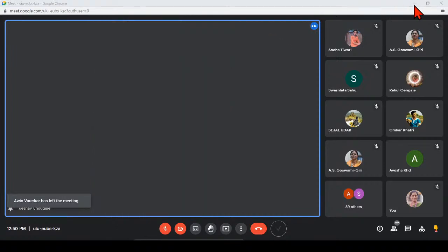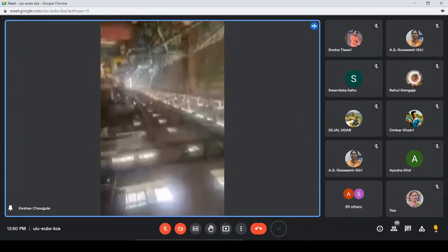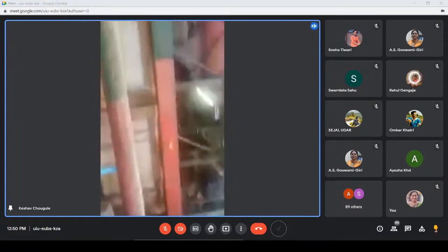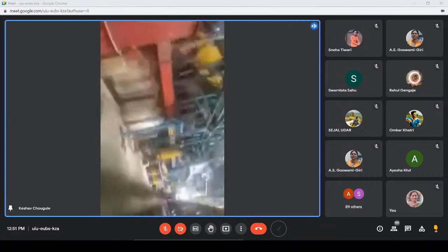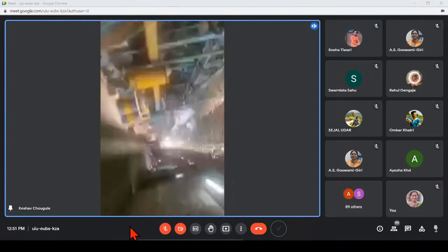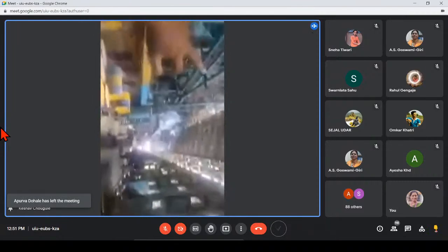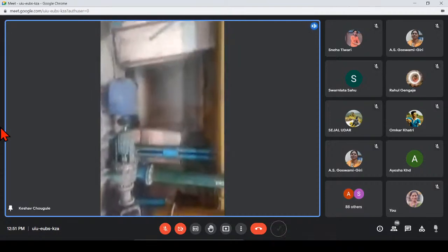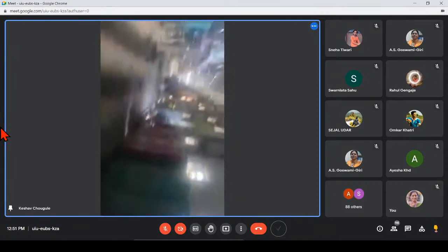See, there are three different mills, and raw juice is stored in that tank, and it is pumped using this AC motor. There is a 10-inch pipe, and by using that pipe the motors pump in the forward direction. There is one mill, another mill. See, there is a roll crusher. After that they spray hot water to extract 95% of the juice from the sugar cane, and all the rollers and the juice tank pump all the juice in the forward direction to the vacuum pans by using these different motors, and these motors are driven by this control panel.